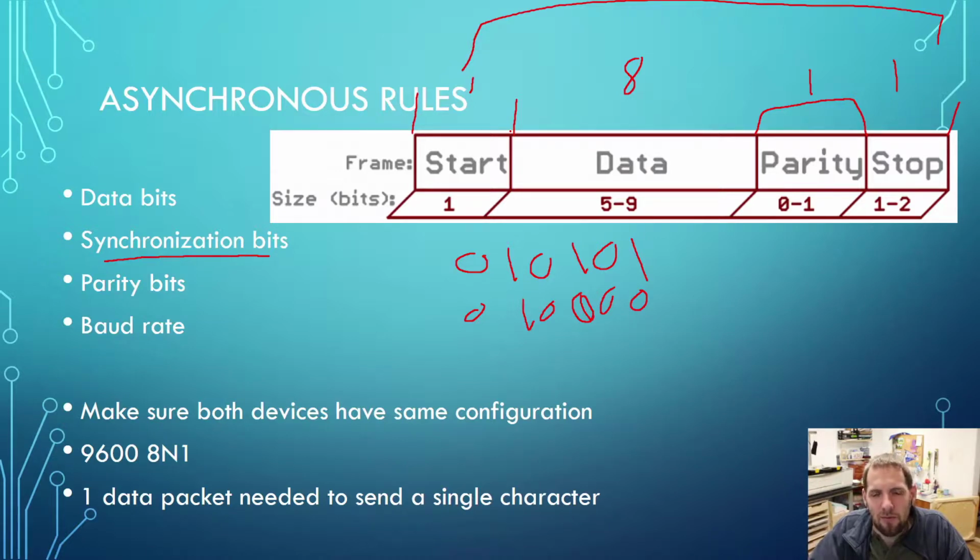So you can see how that really can slow down your transmit time. In an ideal world, you want your data bits to be as big as possible and your stop bit to be as small as possible. And if you're not having any errors, maybe you want to disable parity. Maybe you're like, parity isn't doing anything for me, so we're not going to send anything there. Something to contemplate, so that way you can shrink down the amount of bits that you're sending.